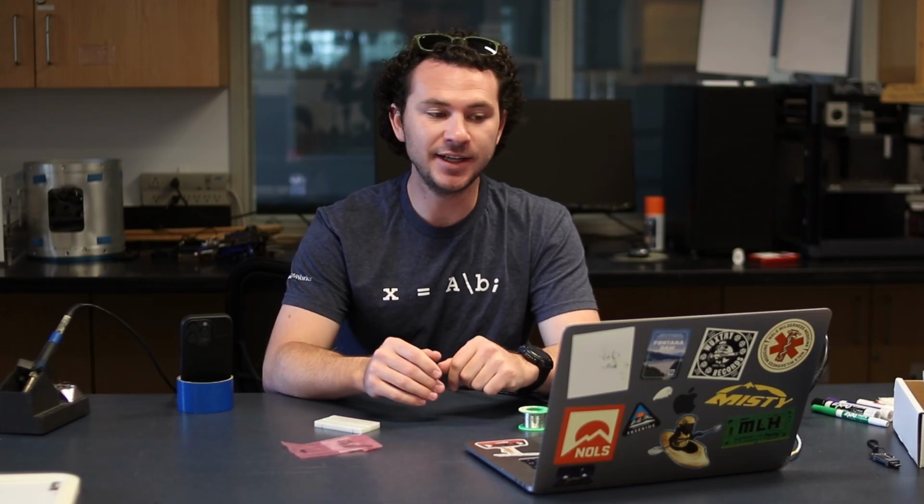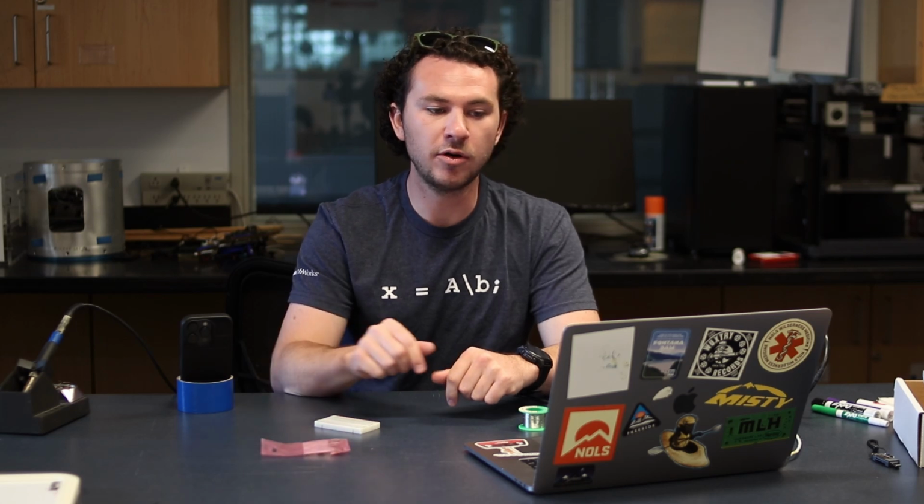As long as we get that set up properly, we're free to use other methods provided by the serial class, such as read, write, and println, to communicate with other devices over UART. Communication protocols give us the ability to network processors, which results in robots that run fast and are easy to modify and repair. We'll practice using a communication protocol, in this case I2C, by connecting an inertial measurement unit to our robot and using it to navigate around an obstacle.